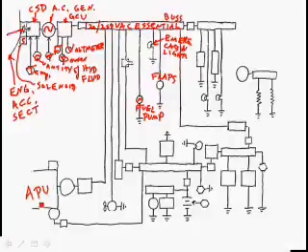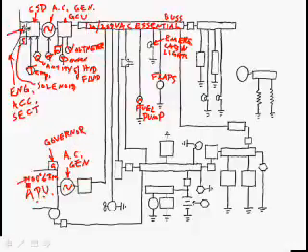Here is our APU, our auxiliary power unit in the airplane. It's going to have an AC generator on it. And you're going, Mr. Johnson, how come we've got a CSD between the main engine and the AC generator, and here the APU goes straight into the AC generator? It's because APUs run at 100% RPM all the time. It's got its own governor,